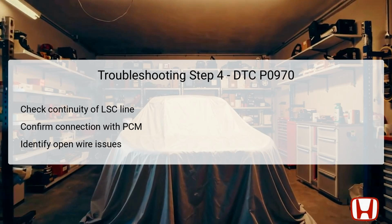If continuity is found between the solenoid connector and the PCM connector B terminals, this indicates that the wire itself is in good condition. However, if there is no continuity, you will need to repair an open in the LSC wire. It's vital to identify the location of the break or fault. This structured approach aids in directly pinpointing wiring issues, streamlining your diagnostics.